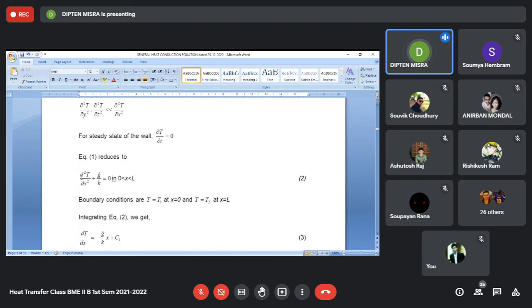Now, when k becomes a function of temperature, then you can write k in terms of some function of temperature. Then this term gets connected to another thing that is connected to t, so it becomes t multiplied by t. Then the power of t to the power 1 does not exist. The power of t becomes more than 1, and it becomes a nonlinear problem.